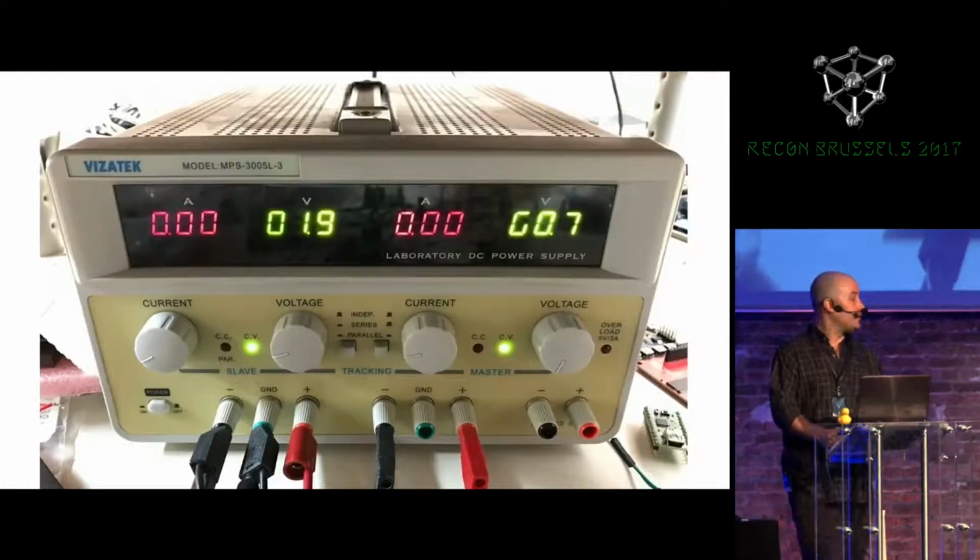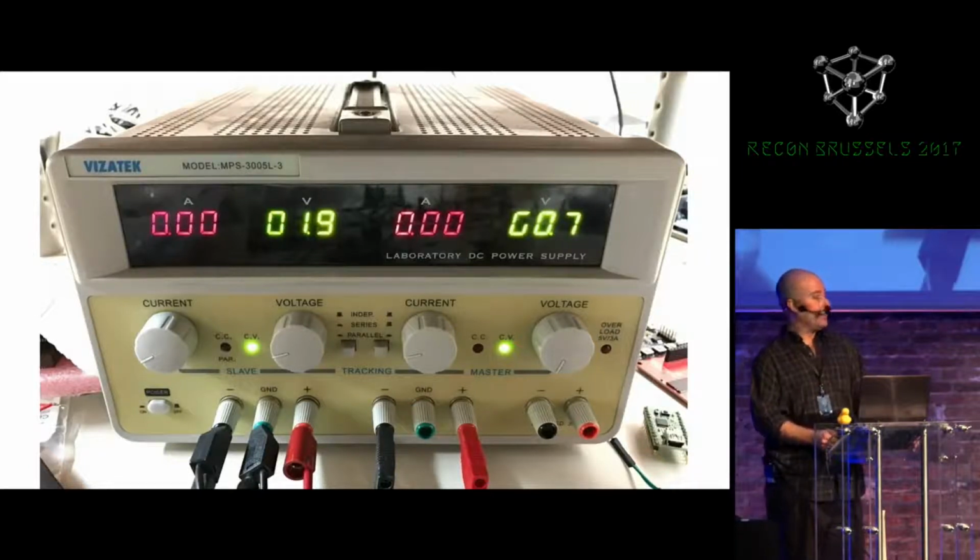For the power supply to control the VDD levels to this chip, I use a benchtop power supply. So it has two outputs. The first output, I can set the normal VDD level that the chip will run at, and then I'm going to use the second output, and that's how I'm going to adjust the level of the voltage drop while I actually perform a glitch on the chip.